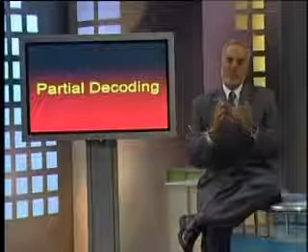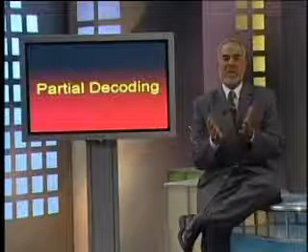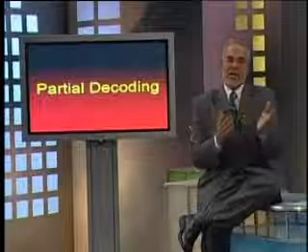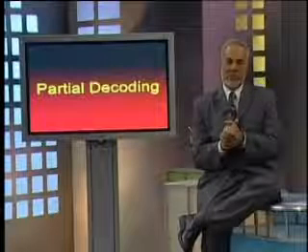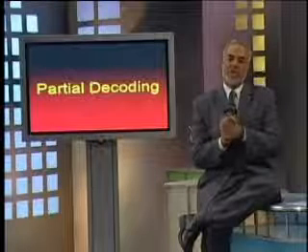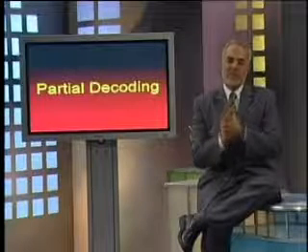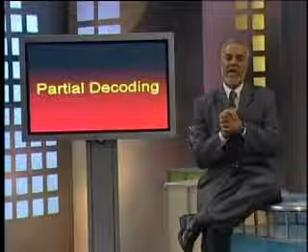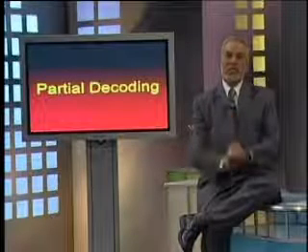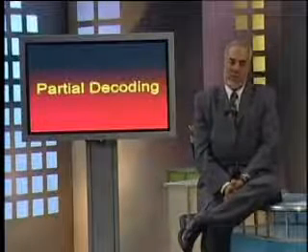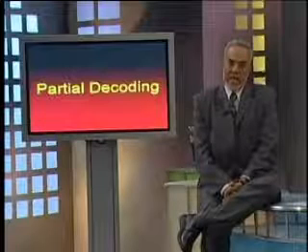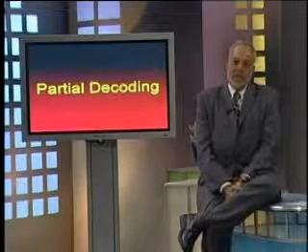Now, if we want to increase this addressable space, we can do that by including more address lines. As an example, if we do away with top 6 address lines and use the 10 address lines from A0 up to A9, then what would be the addressability?